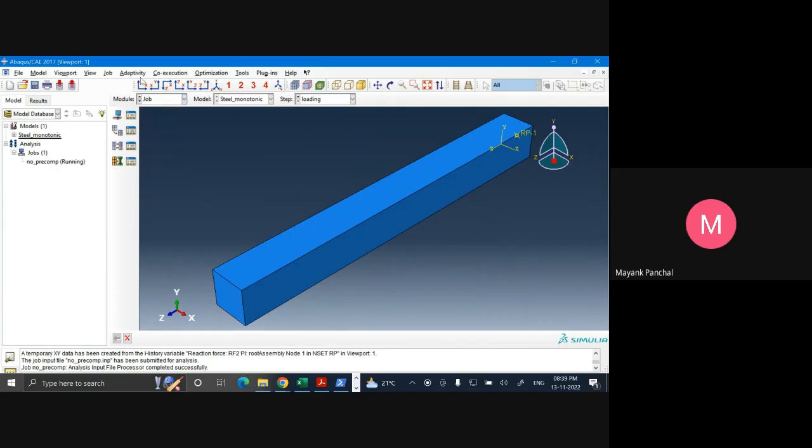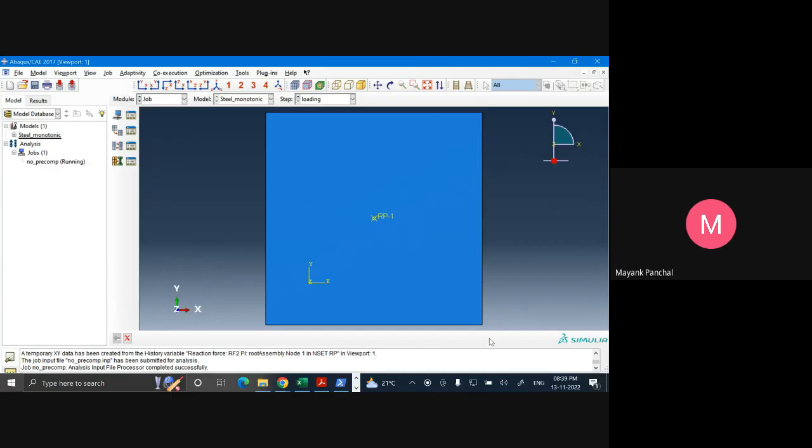Now what you can do is you can replace it, as I told you, with I section. So keep it 500 by 500. Keep the thickness as 100. So it will be 100 like this and 100 like this. Then you can replace it with T section. So this is 500. The thickness will be 100 here. So you will maybe 200 from this side in the middle. It will be like this. That will be your T. L section I told you 100 again. I section again 100 and thickness. Then once it should fail, we will see at what displacement it fails. Then you can compare the sections.